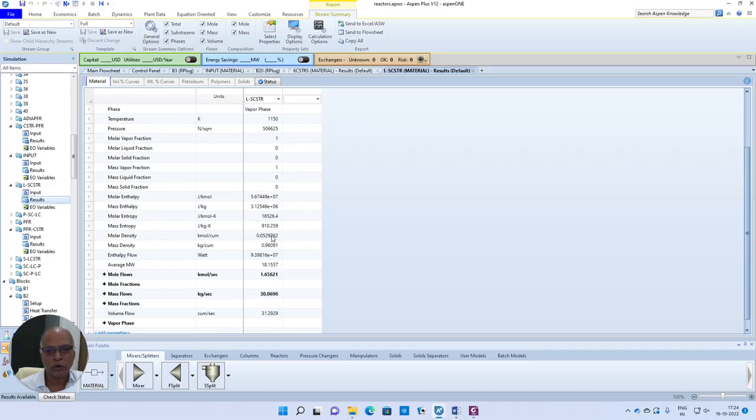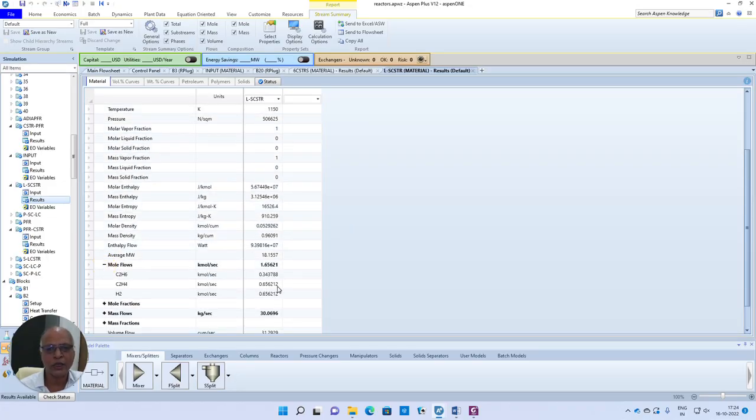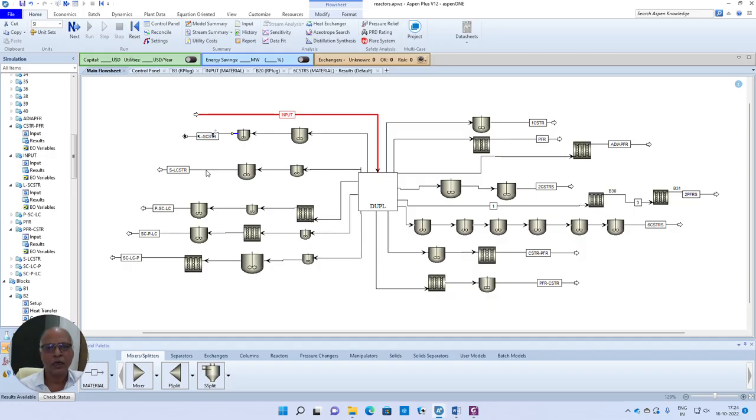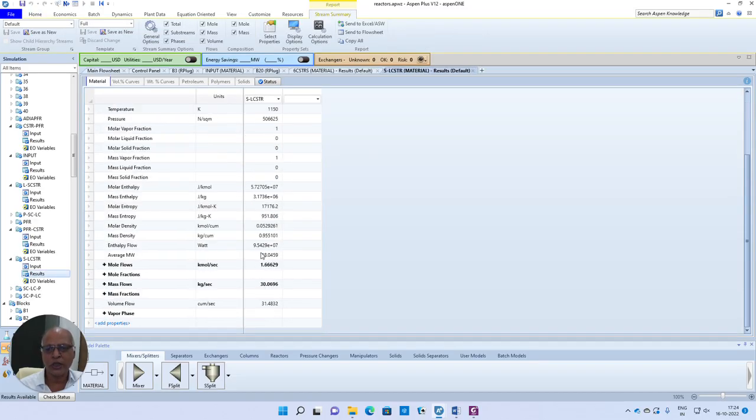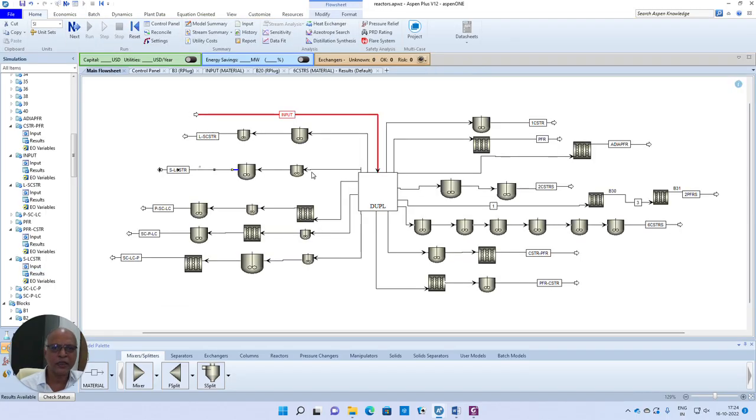So this is giving us a conversion of 65.62%, a small CSTR followed by a large CSTR, whereas a large CSTR followed by a small CSTR is giving us 65% conversion. Small CSTR followed by large CSTR should give us a better conversion than that. So it is about 66% conversion. So like this, you can simulate many reactor models.